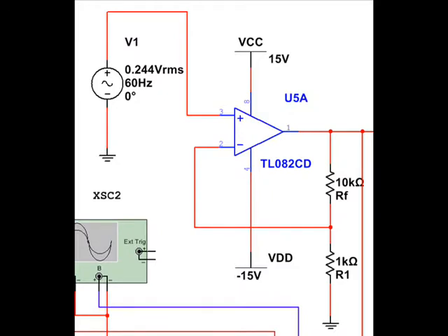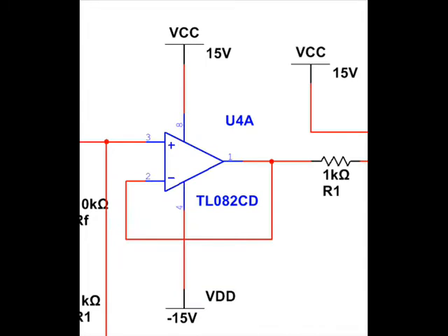First, in the simulation, as we don't have a current transformer, we simulate the output voltage in the secondary with an AC power source. Second, we set an operational amplifier non-inverter to grow the input voltage. Third, we set an operational amplifier voltage follower to keep the input voltage.